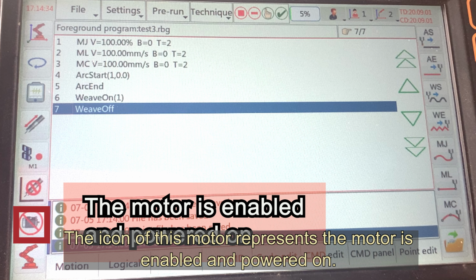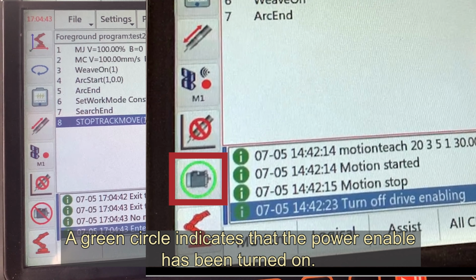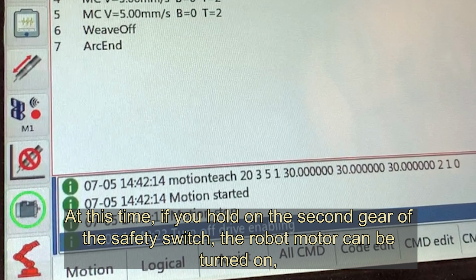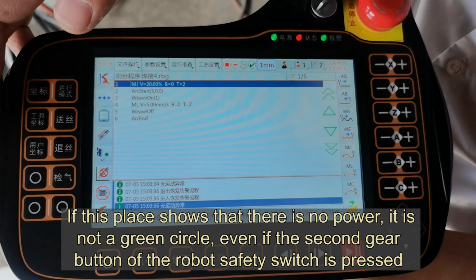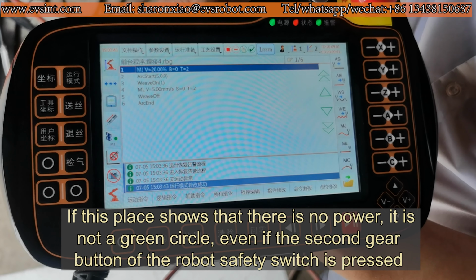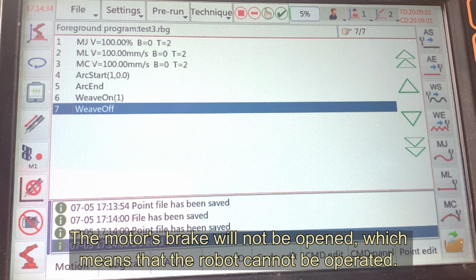The icon of this motor represents that the motor is enabled and powered on. A green circle indicates that the power enable has been turned on. At this time, if you hold down the second gear of the safety switch, the robot's motor can be turned on and the robot can run. If this place shows no power and it is not a green circle, even if the second gear of the robot safety switch is pressed, the motor's brake will not be opened, which means that the robot cannot be operated.